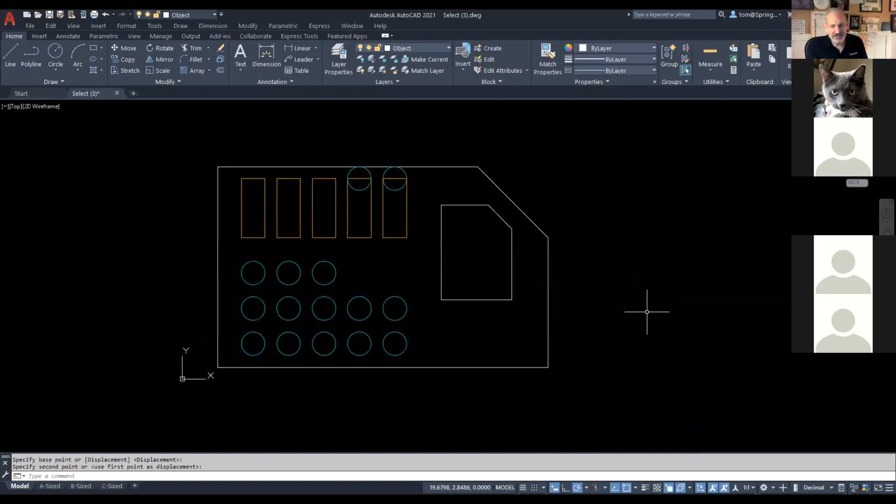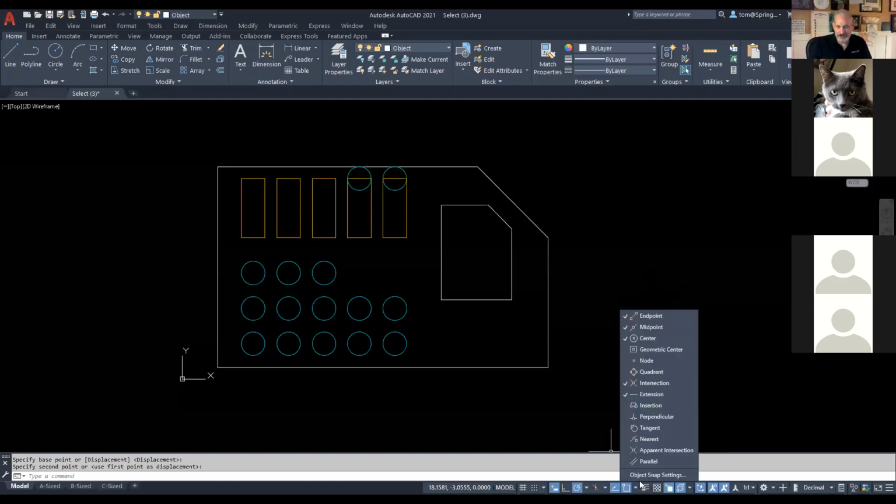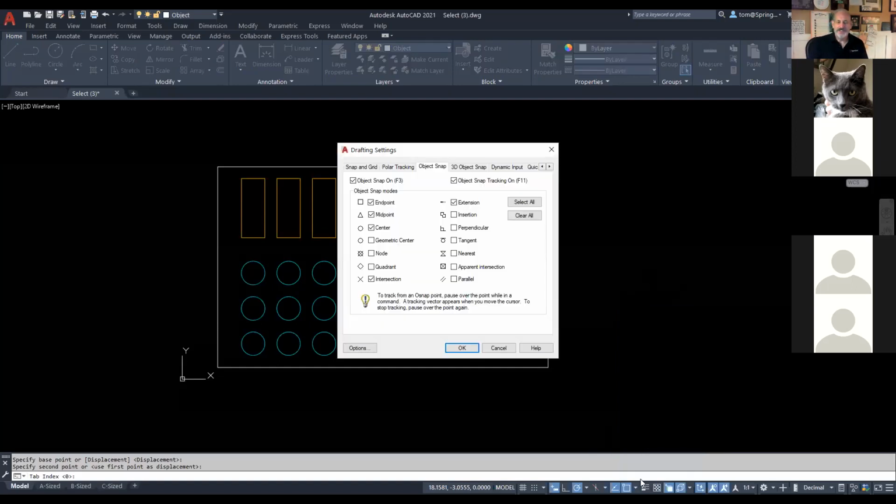Remember what I said at the very beginning, we talked about the AutoCAD tweaks. One thing I should have gone over here, here's something you might even want to take a picture of. In other words, get your camera out right now. If you can, get your camera out. And what I want you guys to do is take a picture of this. That is the default setting of your object snaps. Your object snaps should look like this, or you can do a screen capture however you want to do it. But those are the 5 that will get you through probably 95% of all your projects ever from now till the end of time. That's all you're going to need.